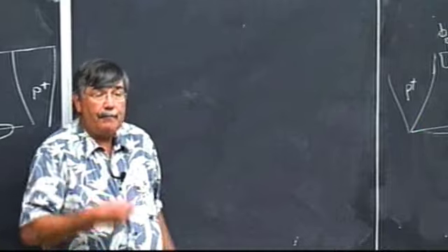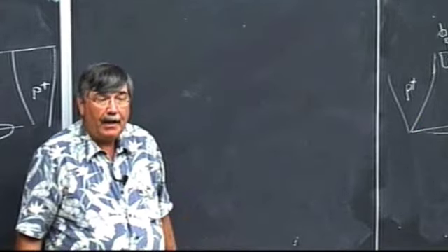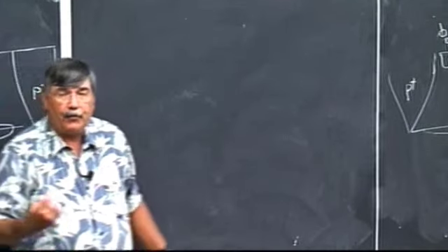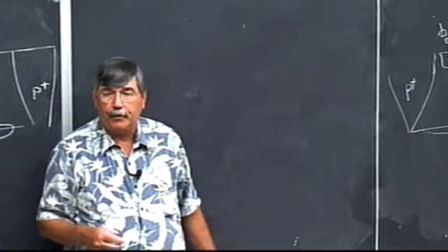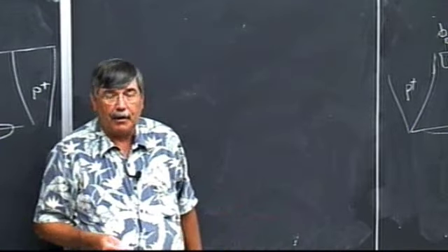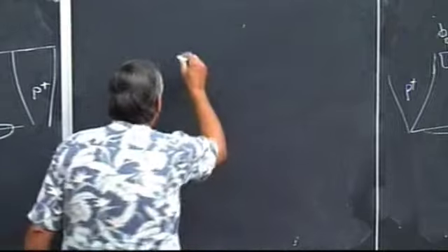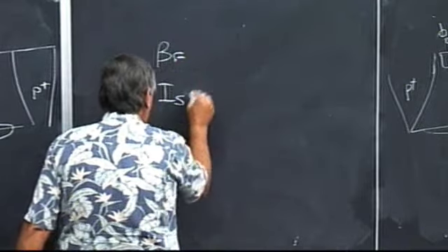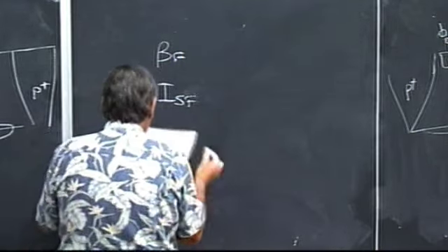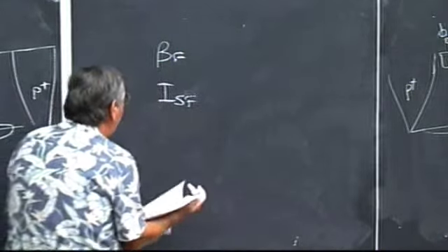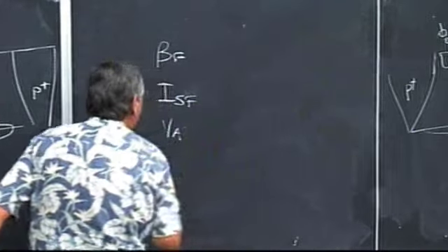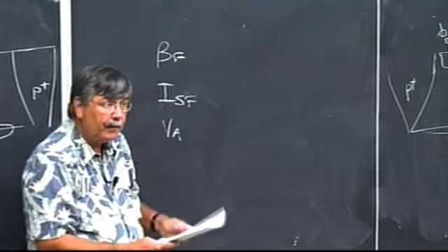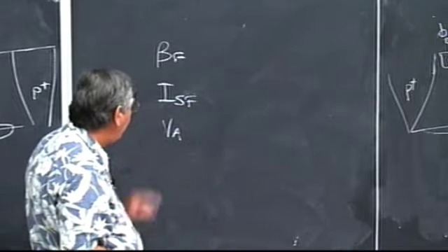When you get it all done, a bunch of optimization happens, and you're going to give a list of 20 or 50 or 100 numbers, and the circuit designers are going to pretend that those are the truth for every device that's ever been made in that process. All right? So what do you have? You have the forward beta. You have the saturation current for the forward direction. Those are the most important ones. The early voltage. Remember, the early voltage told us about how the collector base voltage affected the current. It was a measure of that. The bigger this is, the less effect it has.